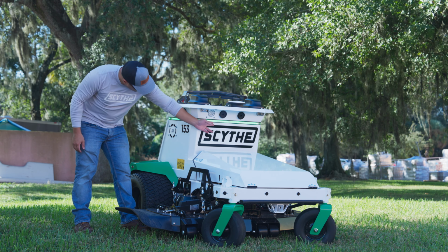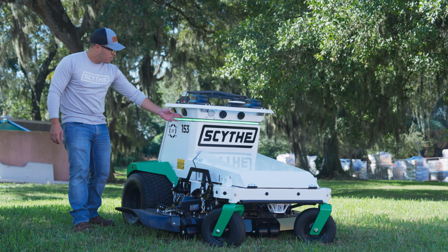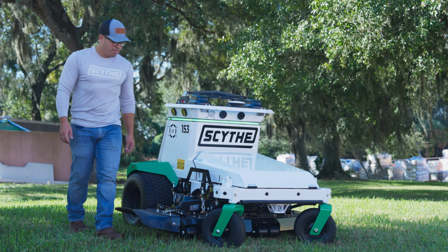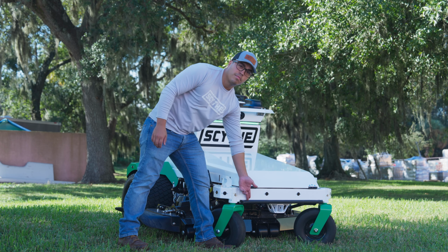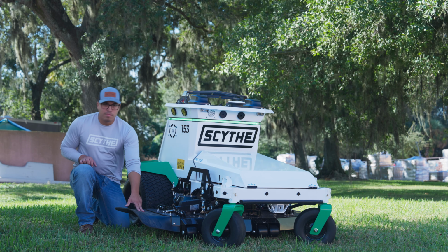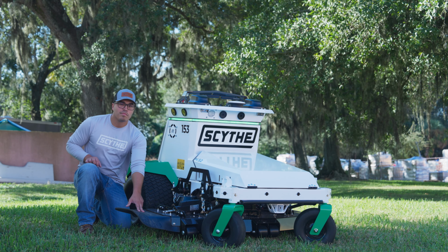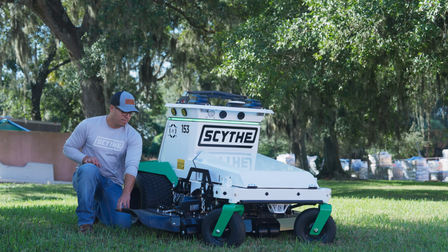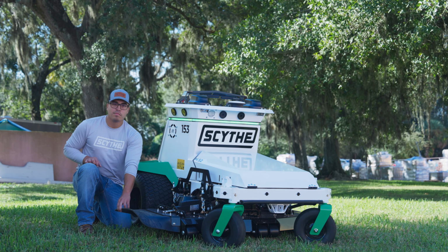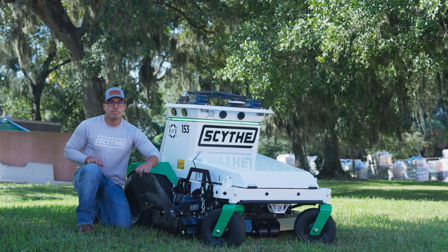There are 8 cameras that provide a 360-degree view around the machine and need to be clean and clear for Scythe mode to work. Along the front of your M.52, there is a bump sensor that must be active and undamaged for Scythe mode to be engaged. Each M.52 comes with a chute attached to the deck for safely directing material as it exits the deck. The chute should remain down whenever the blades are engaged. If the chute is tied up, it may affect performance in Scythe mode.